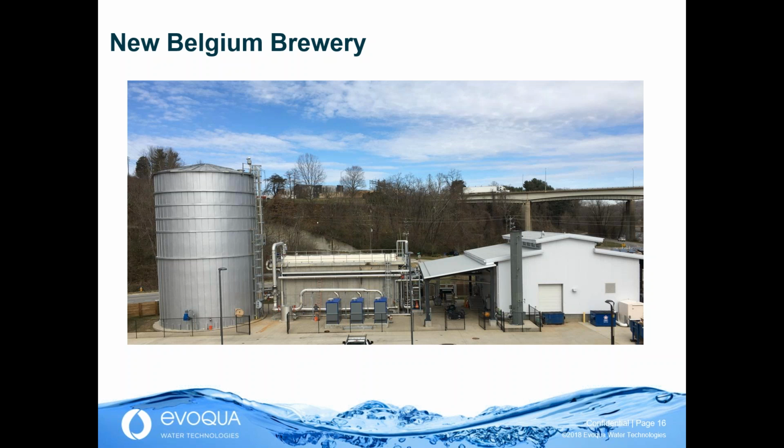typically consists of high concentrations of soluble COD and low concentrations of suspended solids. This composition makes brewery wastewater an ideal candidate for high-rate anaerobic pretreatment systems using granular biomass. Historically, high-rate upflow anaerobic sludge bed reactors or ultra-high-rate expanding bed granular biomass reactors have been the conventional choices for anaerobic pretreatment of brewery wastewater. These reactor configurations minimize space required for wastewater treatment.